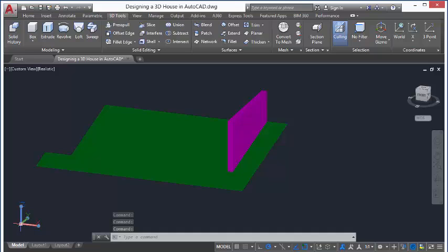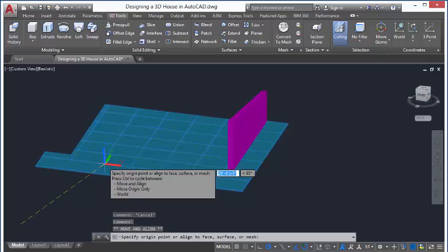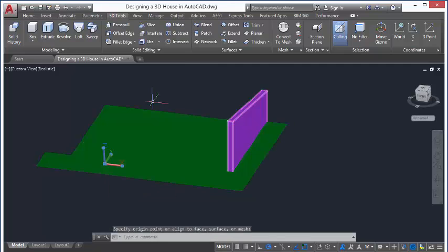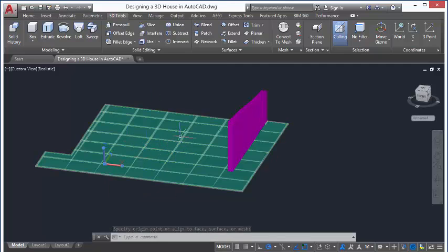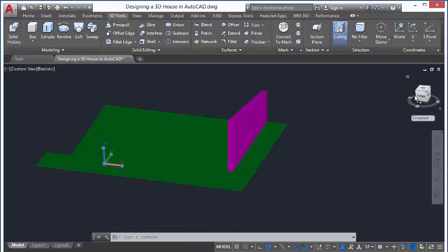Now right click, now select the UCS. When the UCS is highlighted, hover your mouse cursor over this grip and select Move and Align. When you do, AutoCAD automatically aligns this UCS to the surface that you move the UCS to. Click. So now this surface becomes the plane of the drawing. You can tell in the ViewCube because the ViewCube is now slanted slightly.